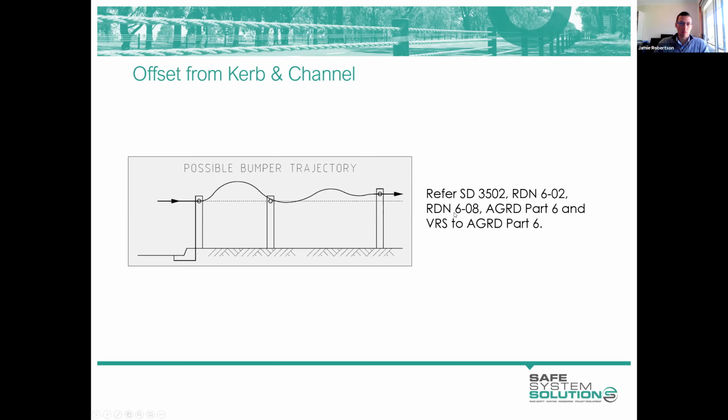Some references there to some guidance on this, but there has been some more recent work which basically says don't install a barrier at this in-between point. So the preference is to locate your barrier quite some distance beyond the curb, something like 7 metres or more, to take out that effect of the vehicle bouncing up and down, or to locate it as close as practicable to the back of curb to capture the vehicle before it's had a chance to bounce up and down. So those are your two preferred locations, here or here.